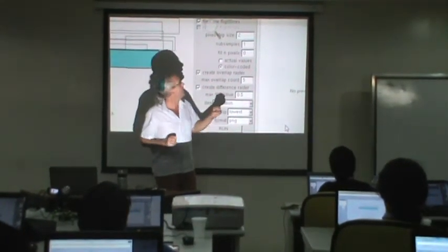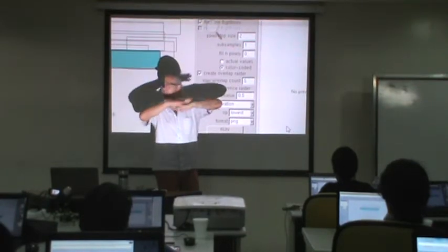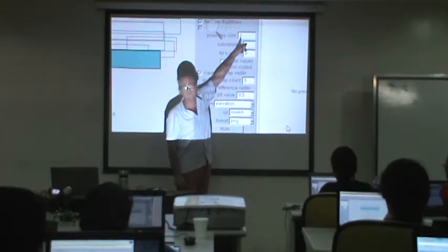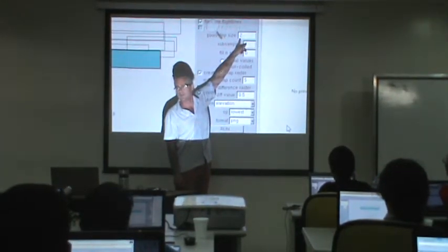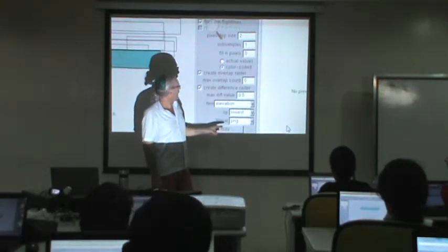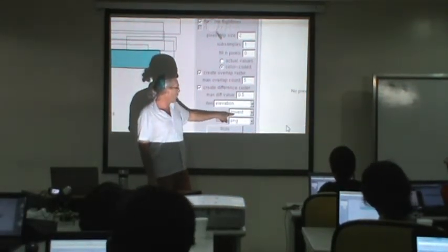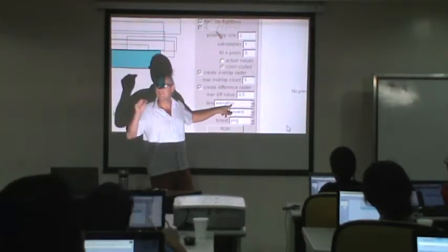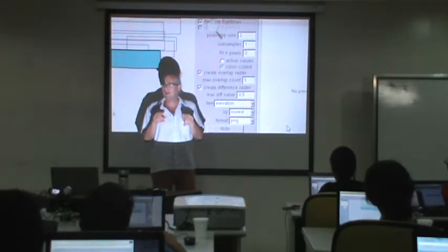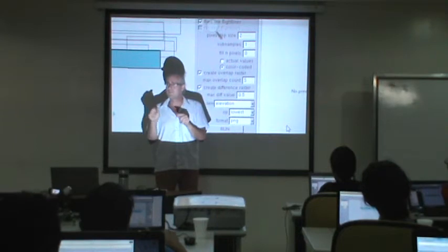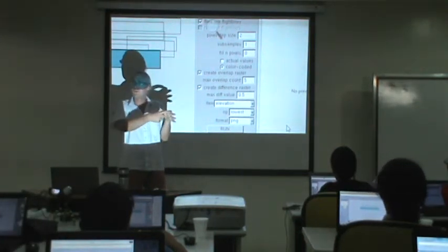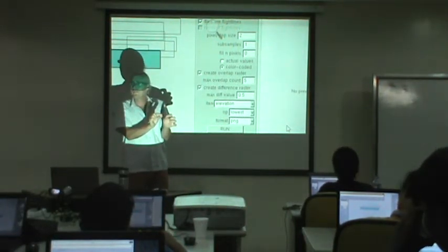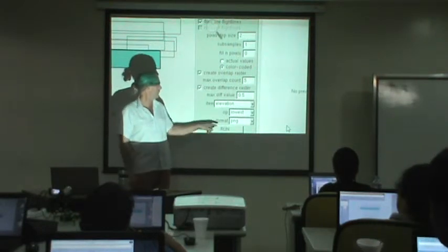That's fairly easy. The other raster, the difference raster, maybe you remember there was this difference raster. The difference raster also takes all the points falling into a 2 by 2 meter cell, and then it looks at the lowest point of all of these points, the lowest elevation, so that's the Z value, for every flight line, and then it computes the differences between the different flight lines that fall into the same cell. So if different flight lines are in the same cell, it looks at their lowest value from all the flight lines and computes the difference.